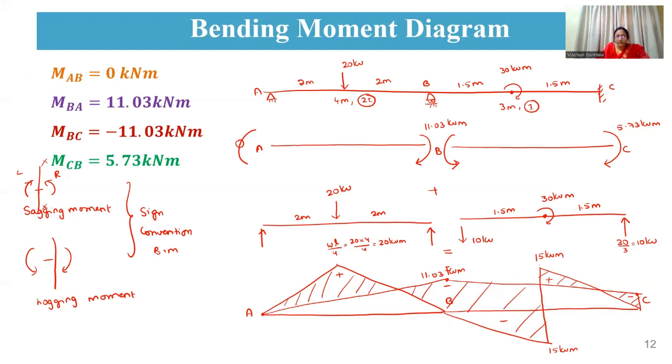So for suppose if you want at this loading condition, the bending moment value will be equal to the total ordinate of this, that is 20. So 20 minus this ordinate is going to give the shaded portion value. So that will be your net bending moment. So this is your final bending moment diagram. I hope you are able to understand this.